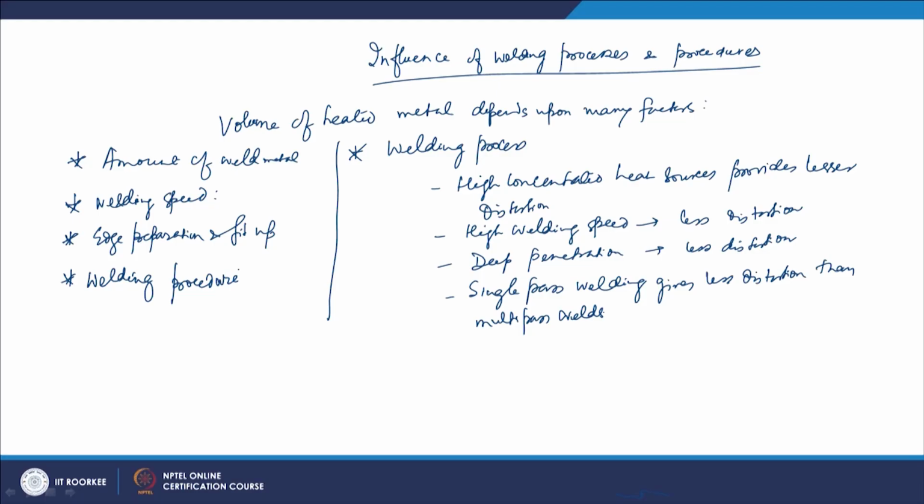So what you see is what kind of process you are taking. We do in the case of skip welding, where we skip the tack welds, we weld in some region, then leave one or two, and then further continue the welding. So these processes are adopted with the aim of reducing the stresses, and once the stresses are reduced, accordingly the distortion will also be less. So this is about the introduction to the distortion.